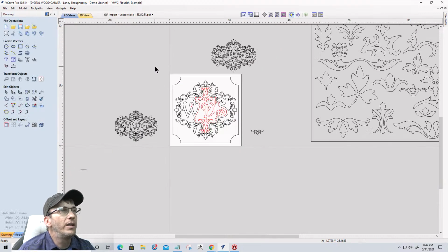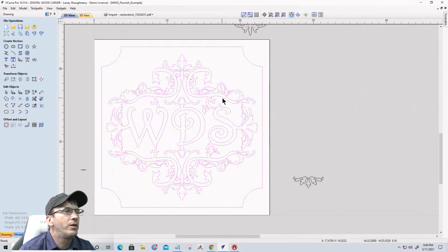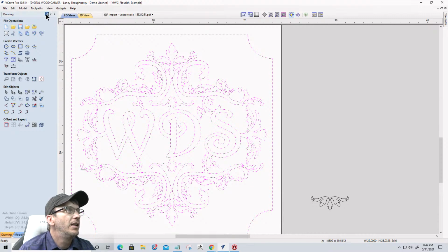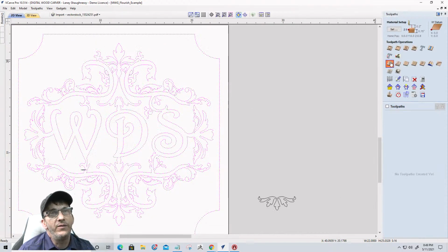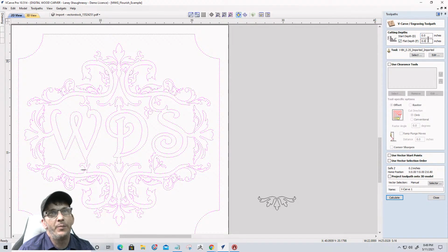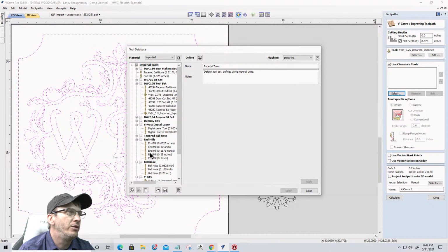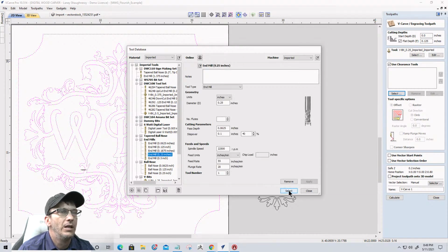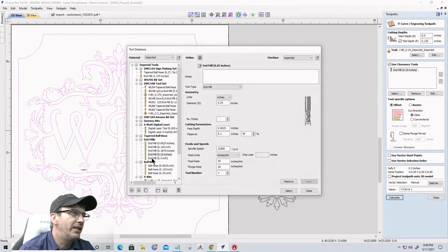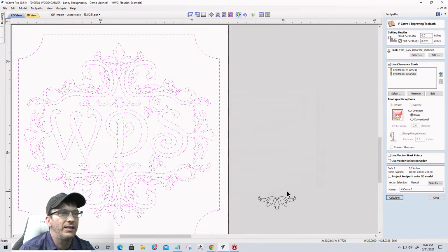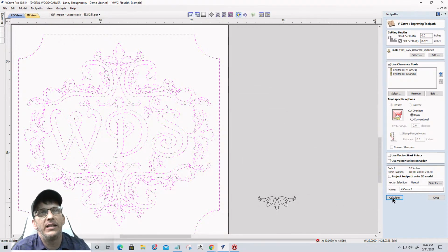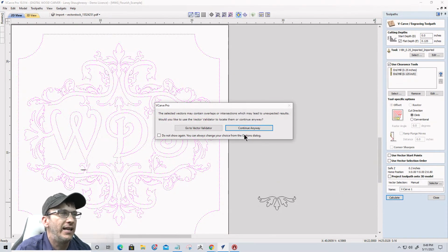All right, if it were me carving this out, I would carve it out just like this, as a V-carve toolpath with a flat depth of 1/8 of an inch. You could even go 1/4, but I'm going to go 1/8. A 60-degree V-bit, along with an end mill. I'll use a 1/4 inch end mill, as well as a 1/8 inch end mill to get into those tighter spots. And I would calculate this as kind of a raised frame design.